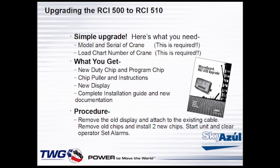Complete installation guide and new documentation, so you'll get a new manual that has the operation, installation, troubleshooting, and calibration all in one manual. The procedure is you just remove the old display, attach the existing cable, remove the old chips and install two new chips. Start it, clear the operator set alarms, and off you go. It's a really, really simple upgrade.